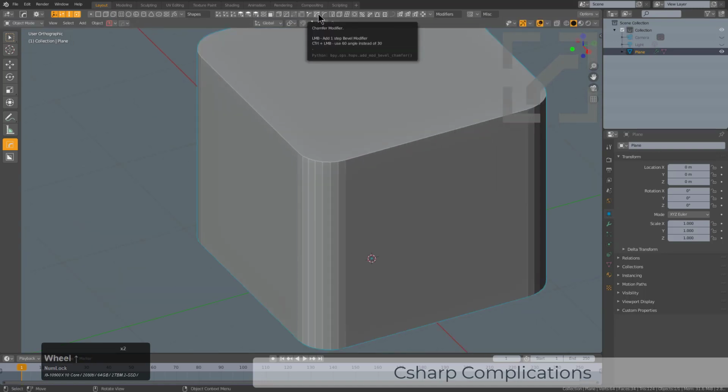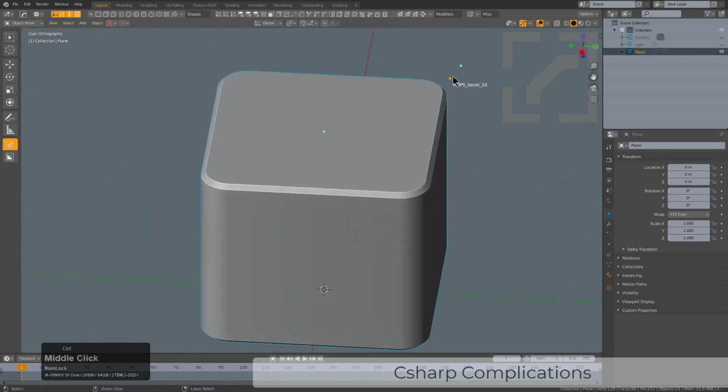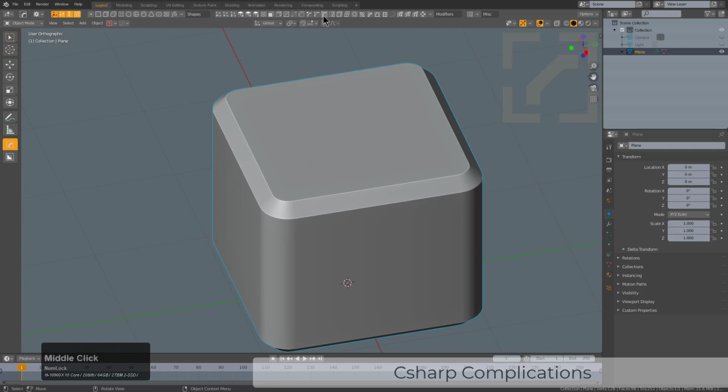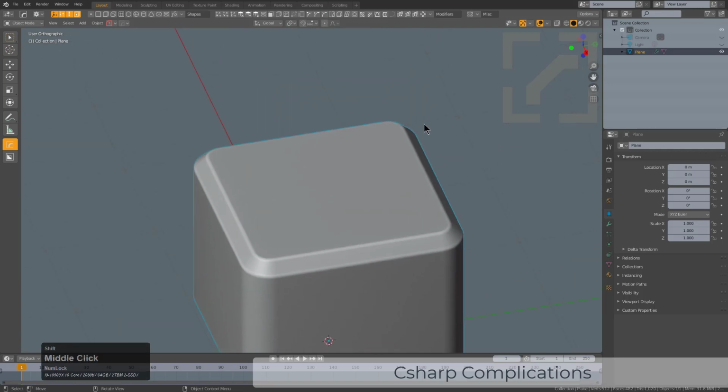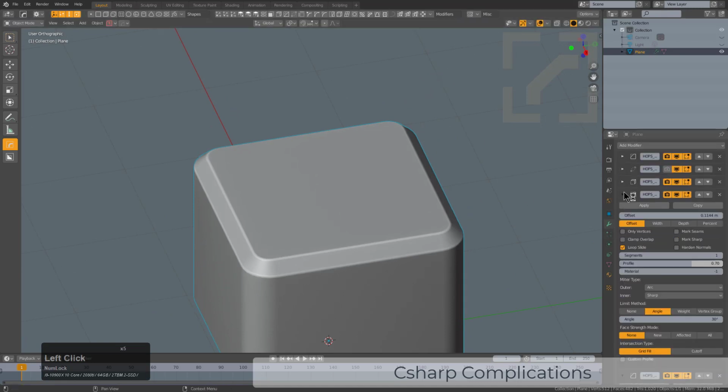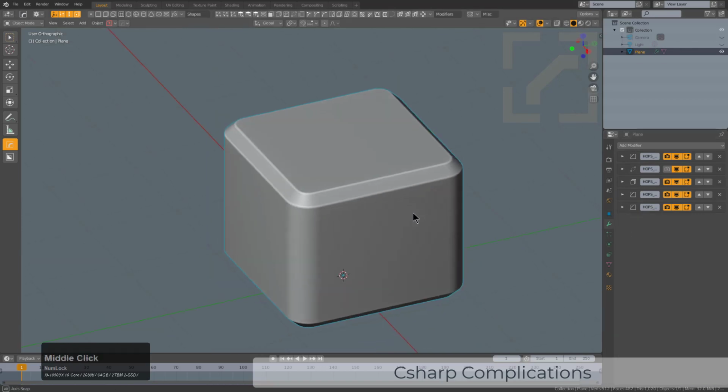And then we'll choose the second bevel dot, which will add a nice chamfer bevel, and we'll grab that dot and just adjust it. And we'll click on this third dot, which will add a 30-degree bevel, and we'll find that dot and adjust it, get it just right. And here we can see the modifiers that we have so far on this particular mesh.